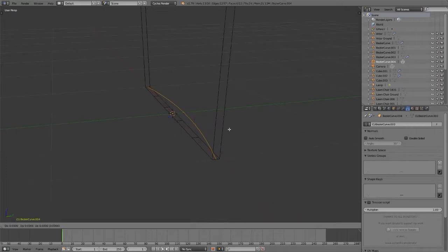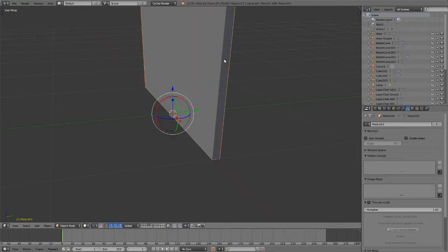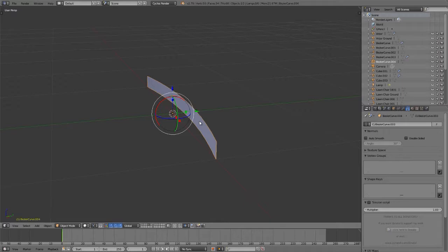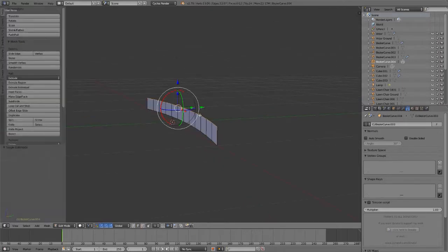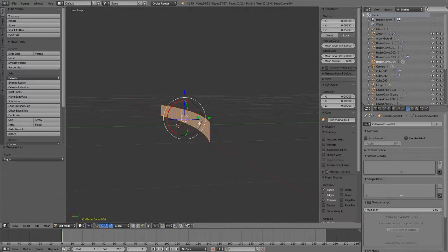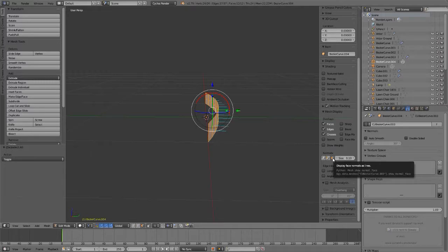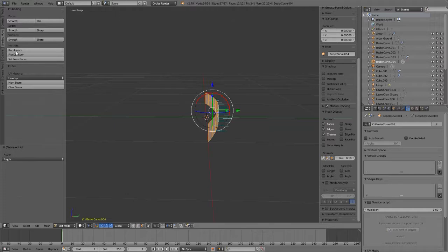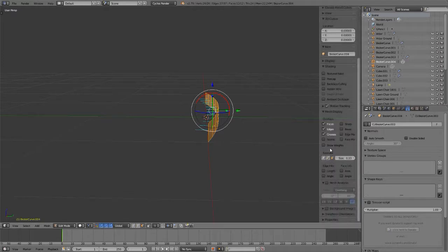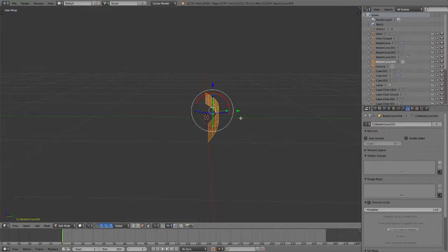Now I'm going to extrude all of them upward on the Z. In shaded view, and without looking at that, that was H to hide it in object mode. When you're feeling shady, and that's your mood, you can go ahead and Control Tab F for faces mode, if you're wondering. Activate the mesh display to see which way those face normals are going. If they're going backwards, and most often, the 2 times I've done this, they go backwards, flip them forward. Good. N and T will hide and reveal the properties for N and the tool shelf for T.